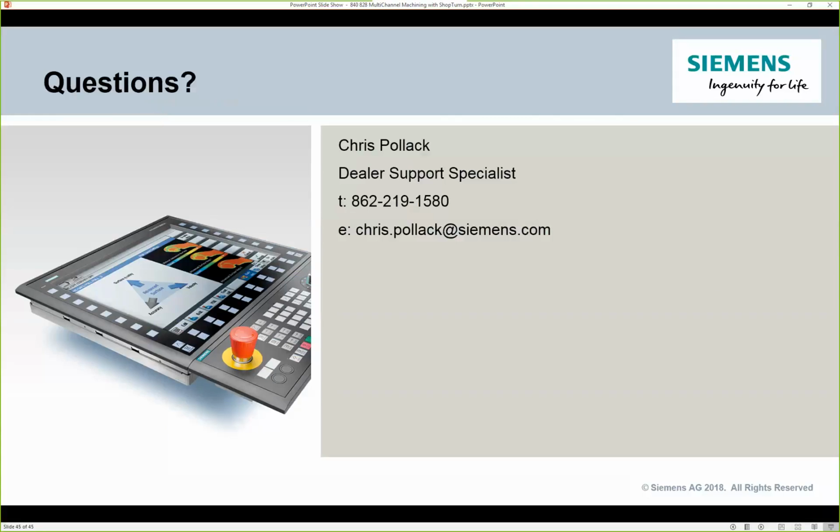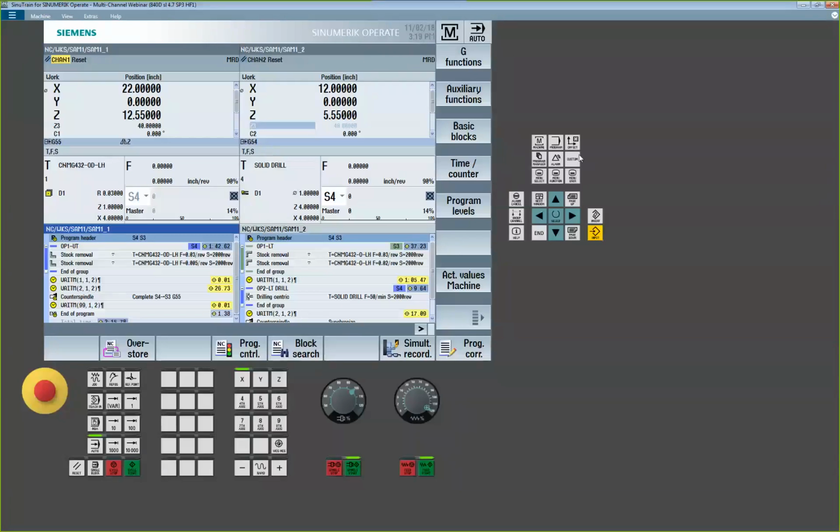Okay, so actually Joseph was asking, he was saying that it's probably a little advanced for this session, but he understands we can do pinch turning. And yes, I'm glad you brought up pinch turning. I'm actually going to be doing a webinar, the next one after this one, that talks about pinch turning in detail. But what Joseph is referring to when we talk about pinch turning is the capability of using the upper and the lower turret to turn on the same spindle at the same time. And then you'd have a lead and a follow scenario. So yes, the system can handle it in ShopTurn or in G-code.